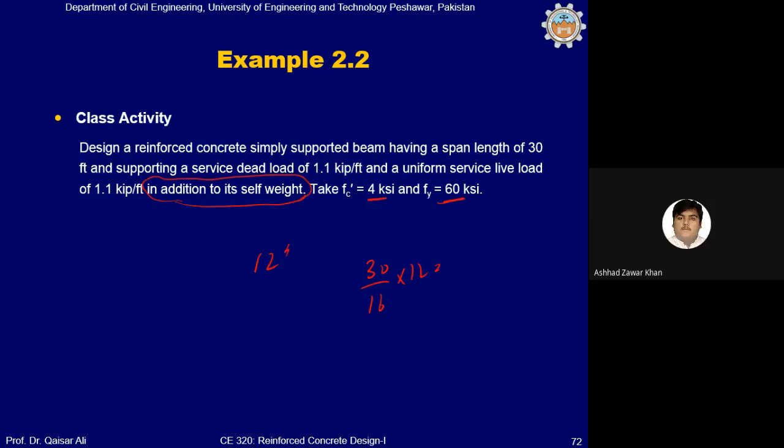Yes, sir, 22.5. Okay, 22.5, but you can take it as 24 inches. Clear. But I will recommend that instead of 24 inches, take 27 inches. So this beam size step I did for you. It is 12 inches by 27 inches.